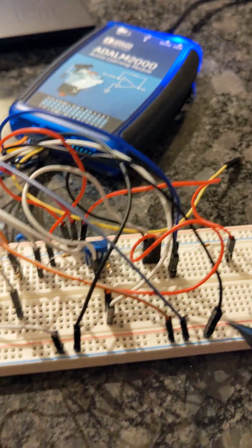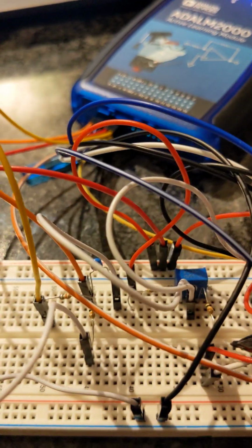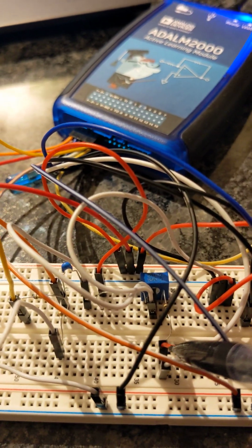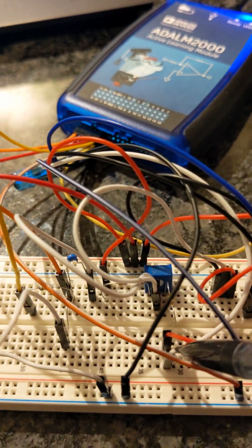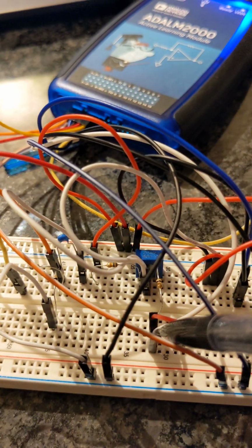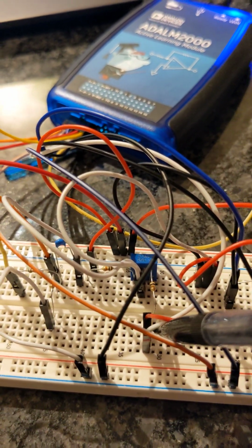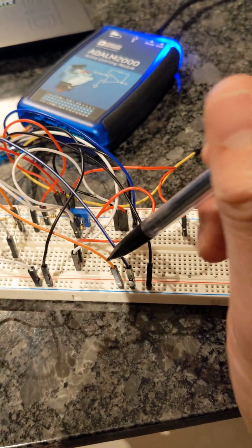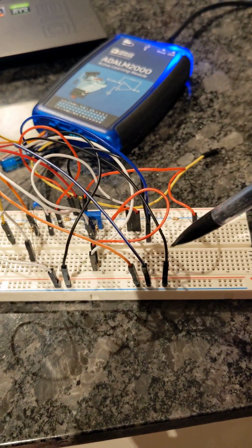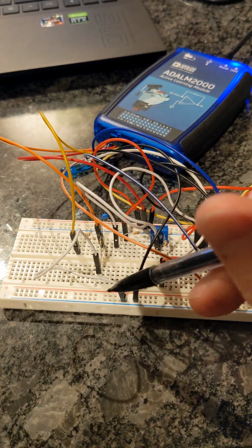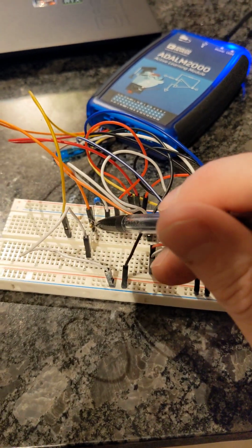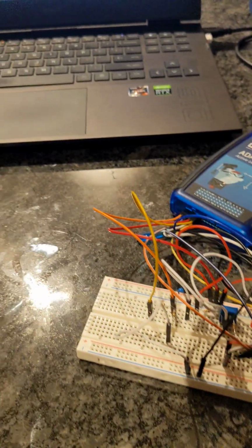And then the source on the right side, we come down where we link up with this bottom of the potentiometer across R4. And then this bottom white cord is our VN, which is -5 volts. Then we ground channel 2 and channel 1 to ground, and then using the other ground. Heck, I don't even need this wire, but the ground of the voltage divider.